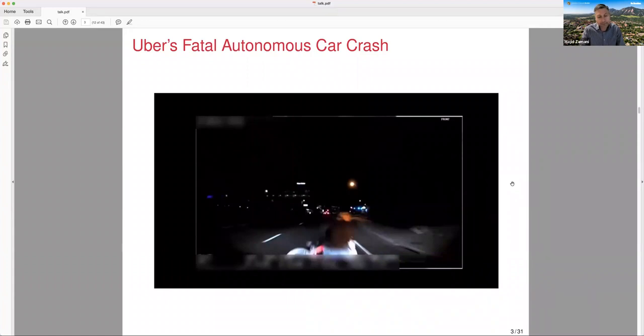She was watching a TV show on her cell phone while she was behind the wheel. The interesting part about this example is that this is not a corner case or rare case in self-driving cars. In fact, the collision avoidance design in the Volvo XC90 would have prevented this crash. While Uber was designing their self-driving mechanism, they disabled the collision avoidance that came by default in those SUVs, which would have prevented this crash. The radar detected the pedestrian perfectly, but the car decided to brake only 1 second before the impact, and that was already too late.